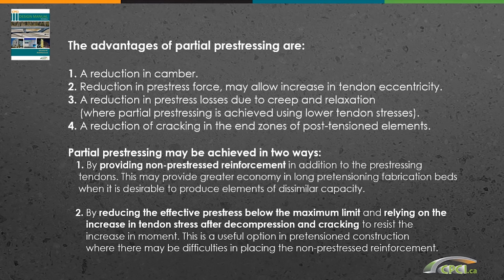But in reality, it's not a bad idea to use partially pre-stressed concrete. Essentially, you allow the value defined by codes for service limit state tensile stresses to be exceeded, sometimes to double the value, and therefore reduce the amount of pre-stressing force that needs to be taken into account, as long as the ultimate limit state is checked finally, fine, and also the crack control issue is kept in check.